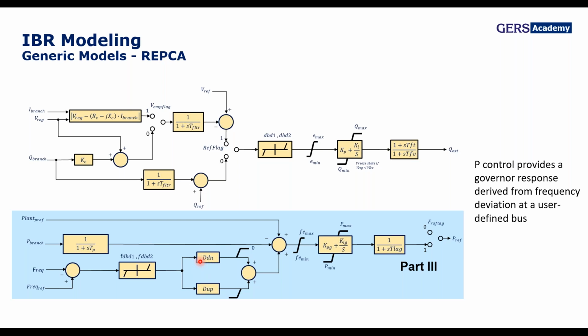Normally, as I mentioned at the start, the PV only responds to high frequencies, making a reduction on the active power that is injected into the grid. But if you want to inject more power as a result of a low frequency event, it will be difficult unless you have some kind of reserve. Otherwise, you will have to work in a state of suboptimal maximum power point.